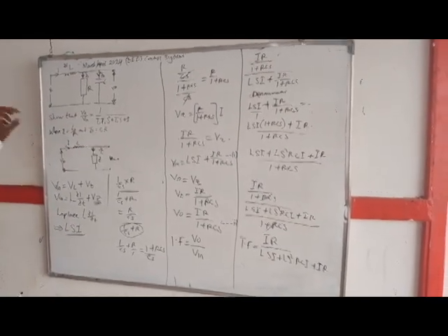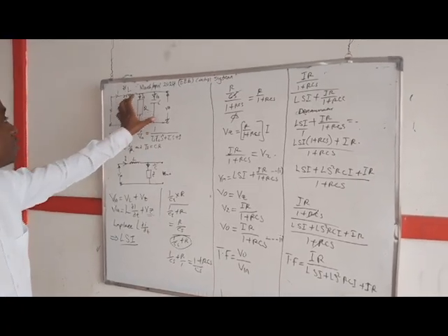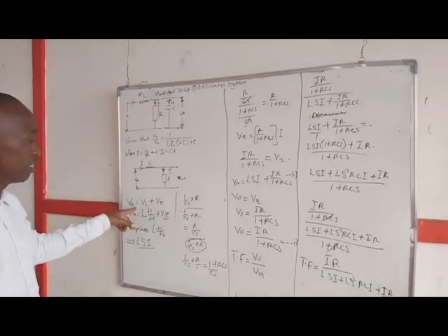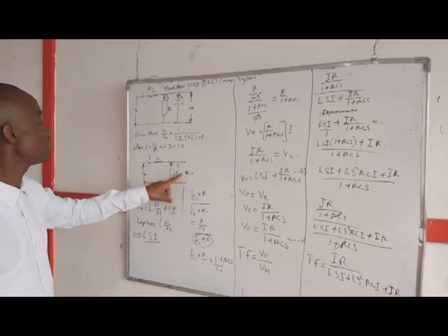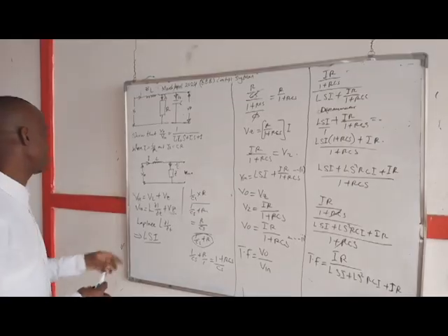First of all, first step, you just combine these two parallel parameters, R and C. Now, for you to get the V voltage input, you have to get the voltage drop in VL and the voltage drop in your parallel parameters, R and C. Now, this is how we go about it.